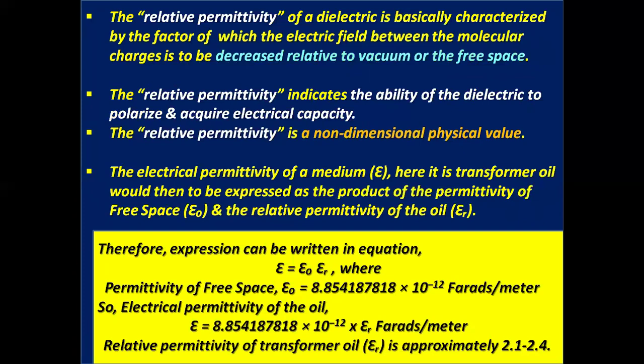the relative permittivity of a dielectric is basically characterized by the factor by which the electric field between the molecular charges is decreased relative to vacuum of free space. The relative permittivity indicates the ability of the dielectric to polarize and acquire electrical capacity. The relative permittivity is a non-dimensional physical value.